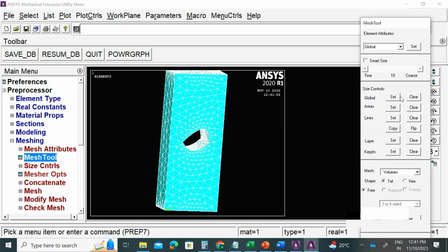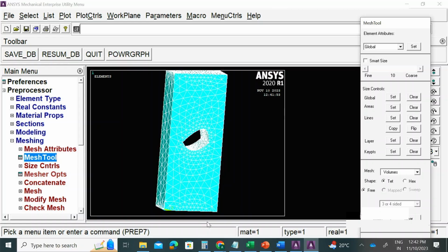We went to the mesh tool and learned about the smart sizing, and also the global sizing control. The benefit of the global sizing control is that it allows you to break down any of the geometrical model edges, meaning any of the lengths and dimensions, into multiple segments and build the elements based on that, right? So we learned how to divide every line or every edge here by 10 divisions or 5 divisions, and how to apply the meshing then to get the right mesh.